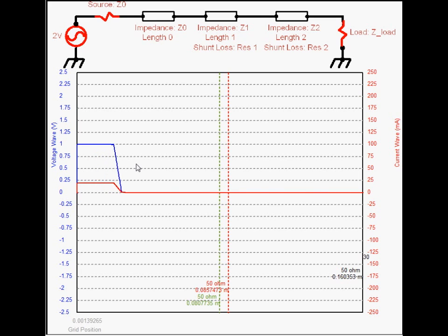For my last case, I'm going to run the 50 ohm transmission line again. Again, the start of the wave looks exactly the same for all cases, but the termination here is 30 ohms. So it's going to be higher resistance into lower resistance, which means a negative voltage wave traveling down and a positive current wave traveling back. And those current waves and voltage waves are going to sum up so that you end up with a steady state case of 0.75 volts and 25 milliamps.